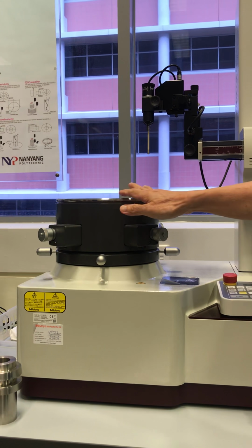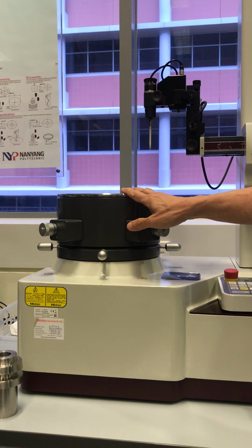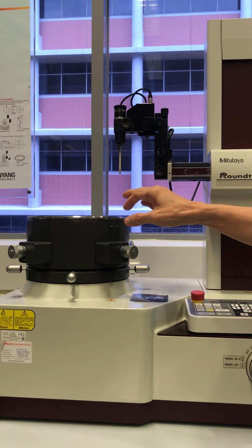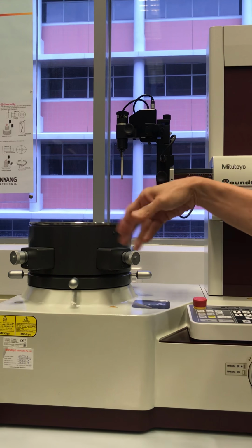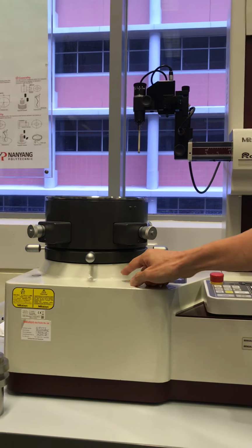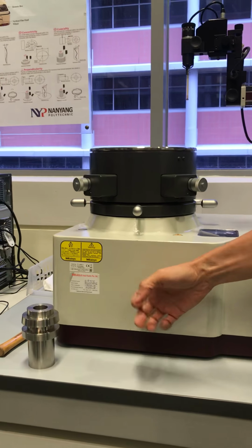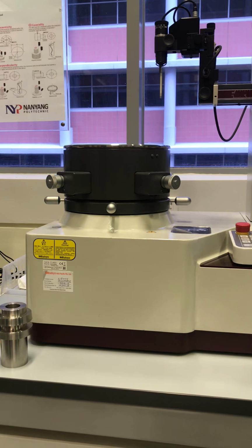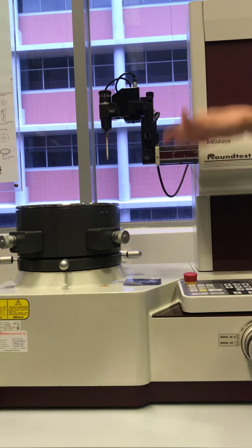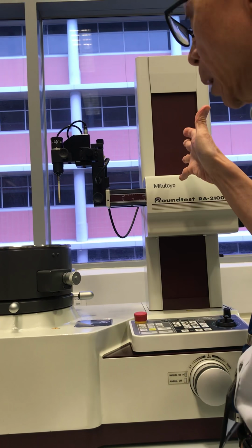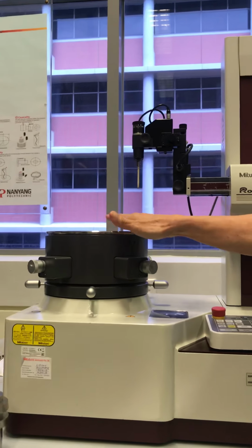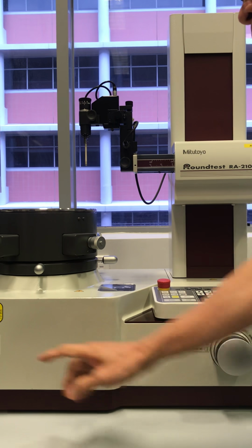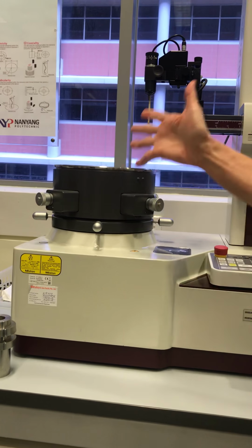Okay, rotary table is a special rotary table. Not only does it rotate, but before you do the measurement, it can help you to do the alignment of the axis with respect to the axis of rotation. So for this machine, the most important thing is the air bearing, which is constructed inside here. Very precise. Every year we need to calibrate to ensure that this axis is parallel to the axis of the whole machine, especially the z-axis, and perpendicular to the table here. This is the alignment table, so that you can align the job with respect to the reference axis.